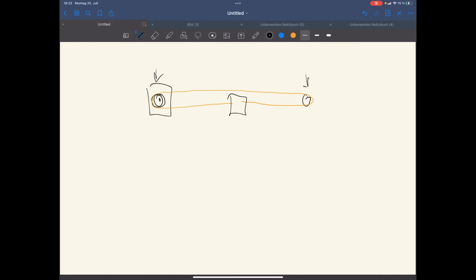And now if we rotate the motor in, let's say, this direction, we move the print head in this direction. And when we do the measurement, we do nothing else than shaking the printer along a defined axis and measuring how the printhead actually moves with an acceleration sensor here. This acceleration sensor compares the actual movement with the one we would expect from this movement of the motor, and therefore is able to see at which frequencies our printer resonates.